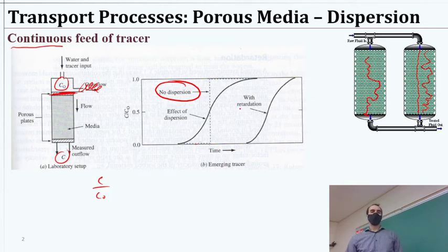And so if stuff's getting slowed down, then water is flowing through this whole time, but the tracer that we added gets slowed down significantly past when the water that we added is coming out, because that's coming out around here. And then the molecules start coming out and have a similar profile there. So that's what we might call retardation in that process. So we often make use of that. We need to understand that if we're going to design, let's say, a groundwater treatment operation. How slowly are these things going to make it through the groundwater? And we'll see an example of that in a minute.